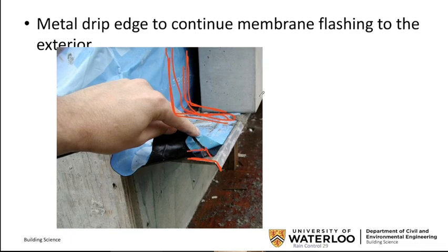And what you see on the outside, this is the cladding panel, right? It's a masonry finish. You see the stainless steel, and it projects out and supports itself. But almost all the water tightness is provided by this hidden membrane, which is protected from UV, but can accommodate expansion and contraction. Before they had membranes, they would have made this piece of metal go all the way back and up. And that is not as effective.